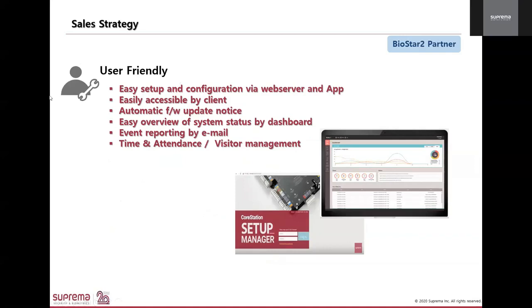So overall, moving along, the user friendliness of our system, right? As you see how easy it is to connect the CoreStation and wire it. Having the color coded wires and the color coded slots on the CoreStation makes it a lot easier to configure. It's easy for an installer, where you could actually just come on site with your laptop, connect directly into the CoreStation web server and basically configure it right there and be done.